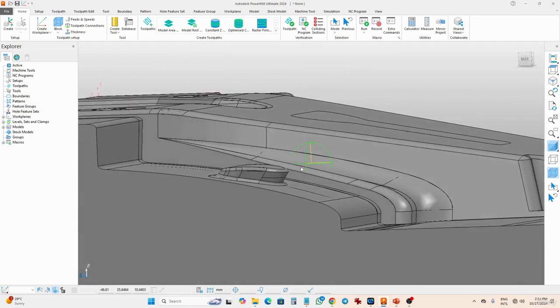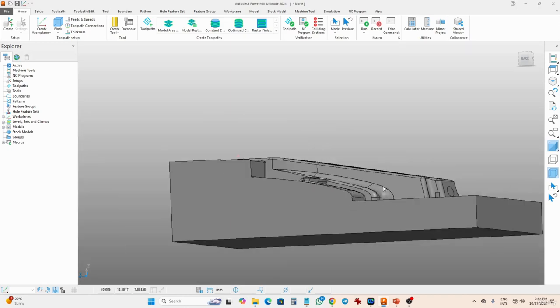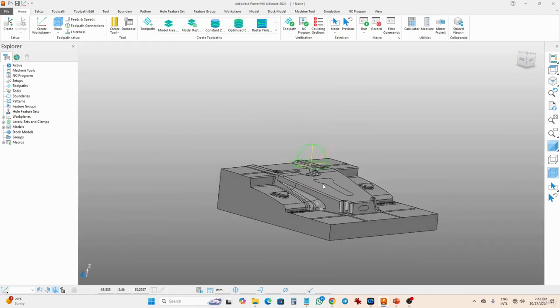The real issue is that the tool is not going to stay in a vertical position. The tool has to enter at a different taper angle position, so this needs to be completed using the 5-axis operation, with some toolpath lead-ins, which we'll discuss today. So let's get started and create this part.